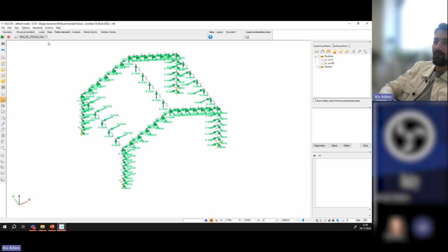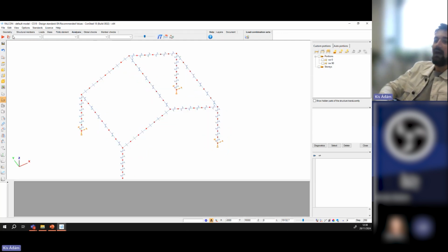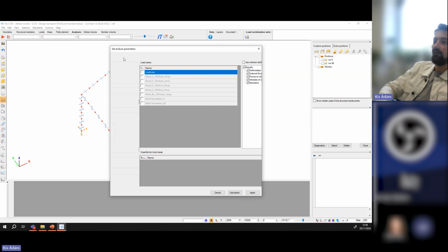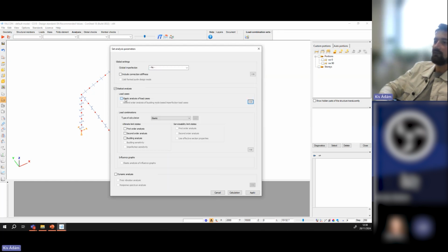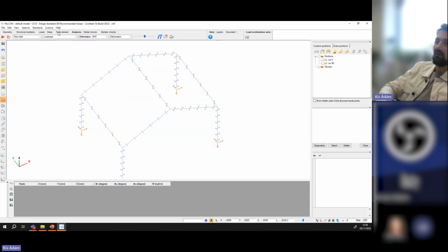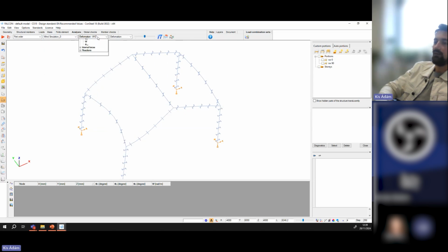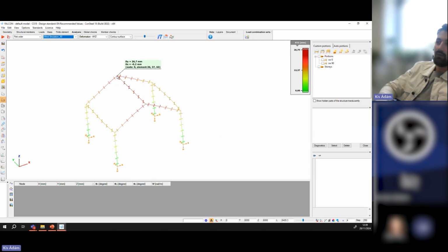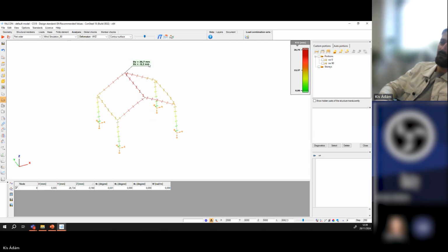And having this finite analysis, or finite mesh with loads, I can run a static analysis for all of the load cases just to see some deformation, maybe to compare them. For example, for simulation 0, I have flexion of the structure. Probably the 90 direction is even more interesting. I have this 27 millimeters in this direction.